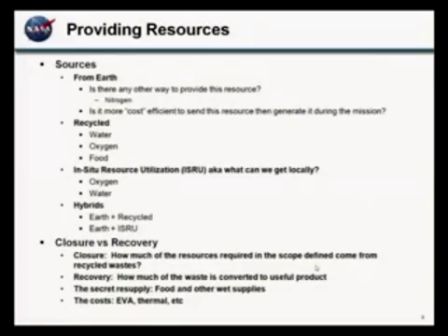And especially for a long mission where you need more habitation accommodations, you're going to have a hard time finding non-flammable options for all of them. So we have looked at argon as something that could be considered. It is another gas that is not going to interact much with the human body, but would keep your flammability risk down.